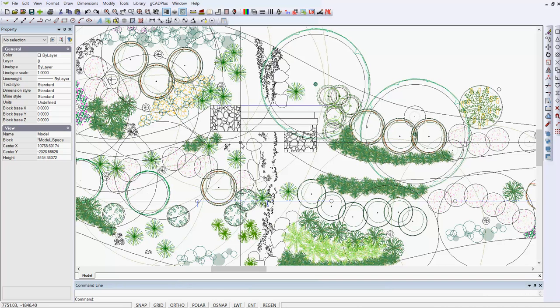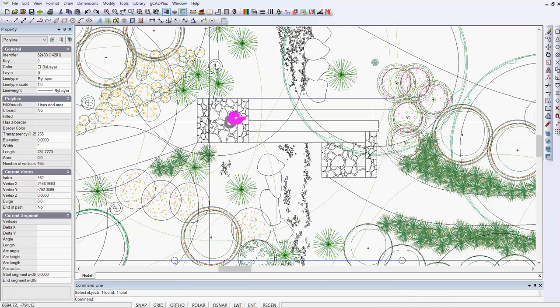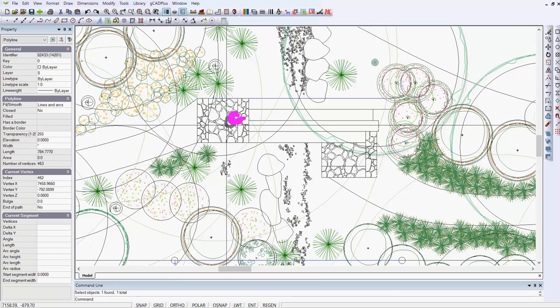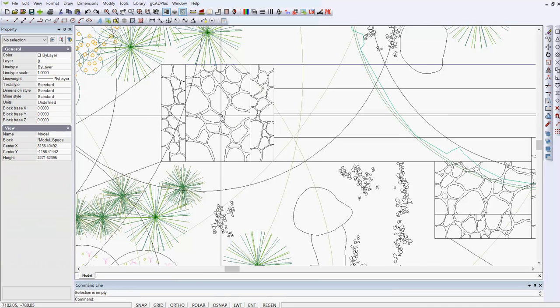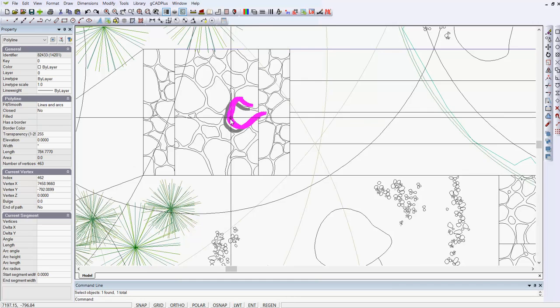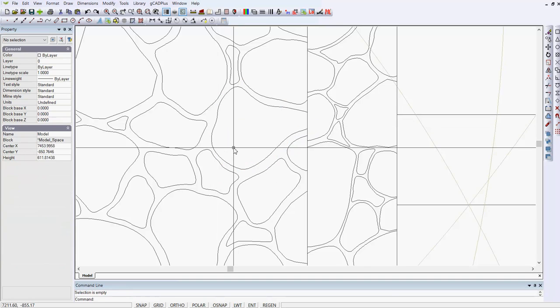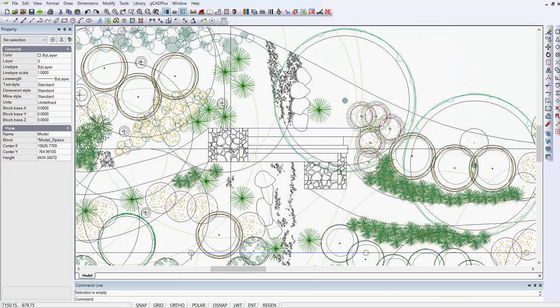So I think this drawing now is stable, although far too big, and the reason that it's far too large is that all sorts of things have happened, that the symbols, I think, have been made far too complex. But if we take the example of this seating here, and we pick what I would have thought was a single element, just one hatching, it turns out that the hatching must have been exploded a couple of times in that middle zone, because elements such as this one, and I think that one there, have a huge number of individual entities in them. It's just a mass of data points, hundreds and hundreds, just on that one curving segment.